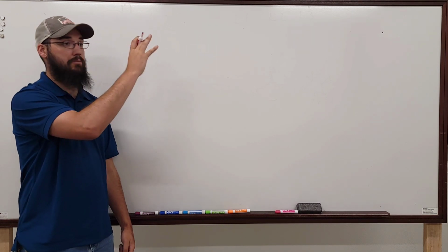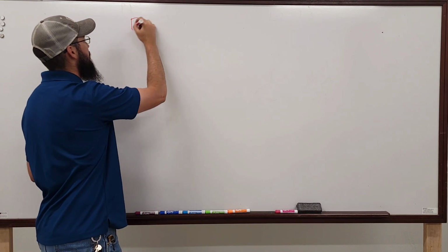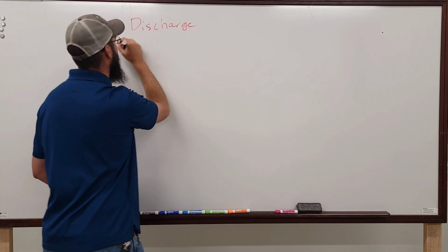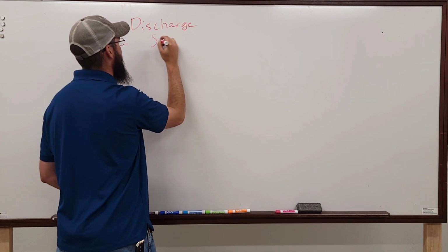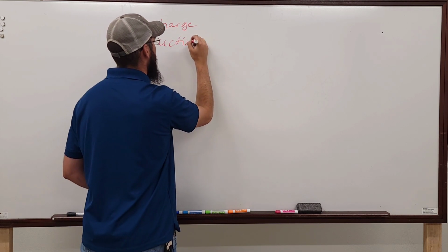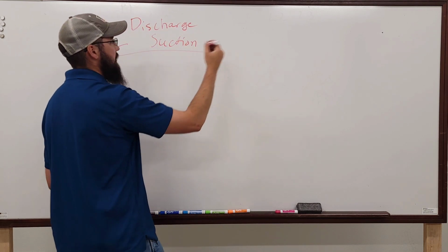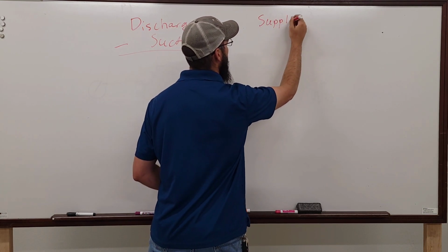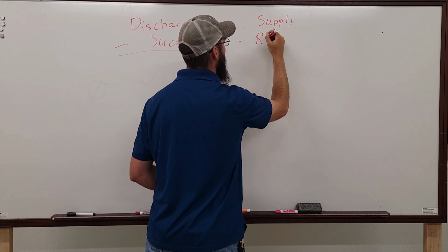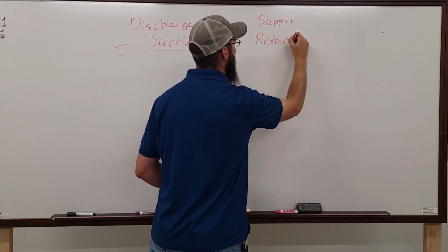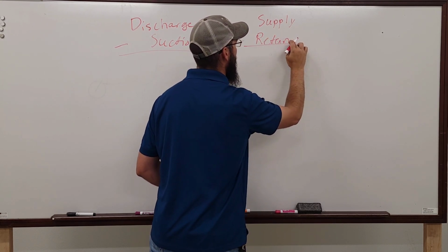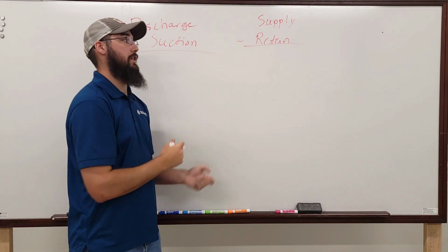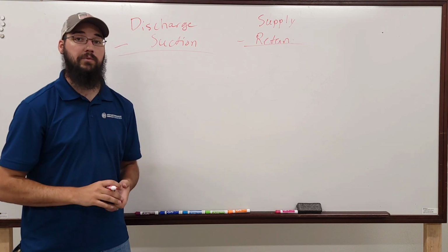It's your discharge pressure minus suction, which in our air handler's case would be supply minus return. Okay? This is where the lift for an air handler blower motor comes from.